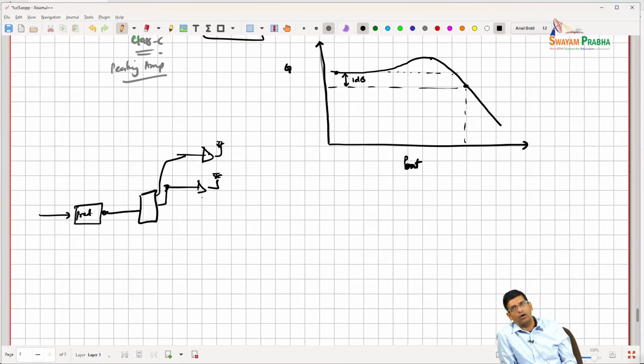So on single PAs, 100%, right, you do pre-distortion, but on arrays, the problem is that you don't have access to it. So this is one of the hidden benefits of building a full MIMO array, because then you can do pre-distortion on each PA level, because each of the streams is different. But all that takes power to do. This is called array level pre-distortion. So folks have tried doing it, right? At the margin it helps because there are some common nonlinearities, so it does help.